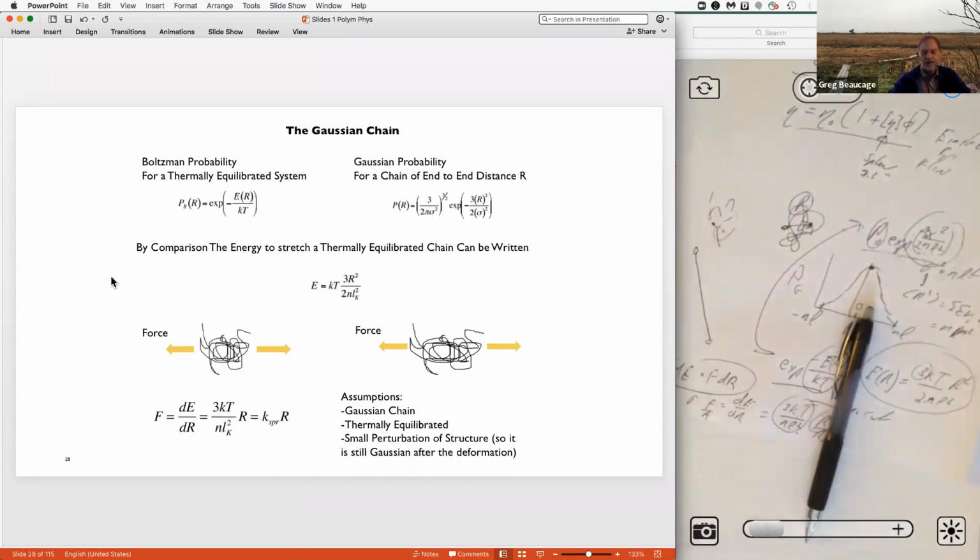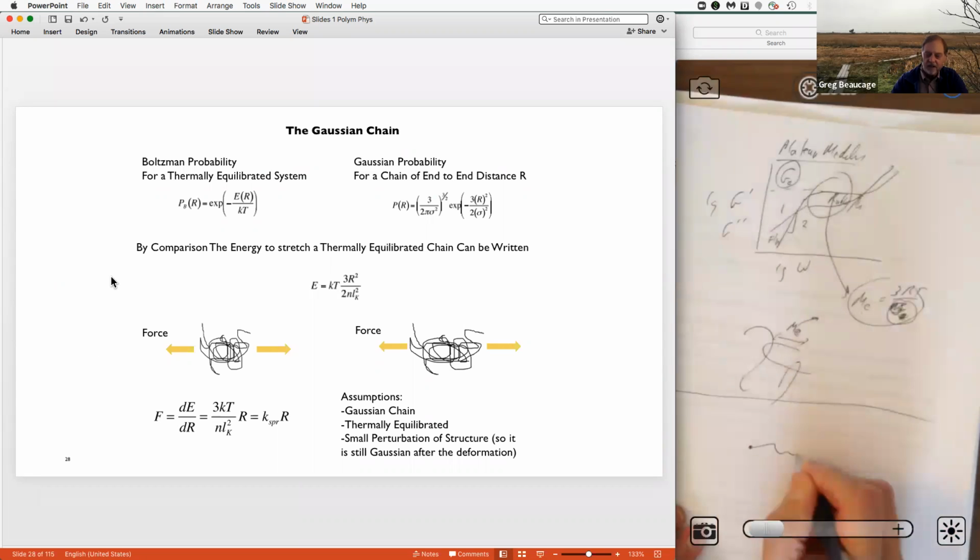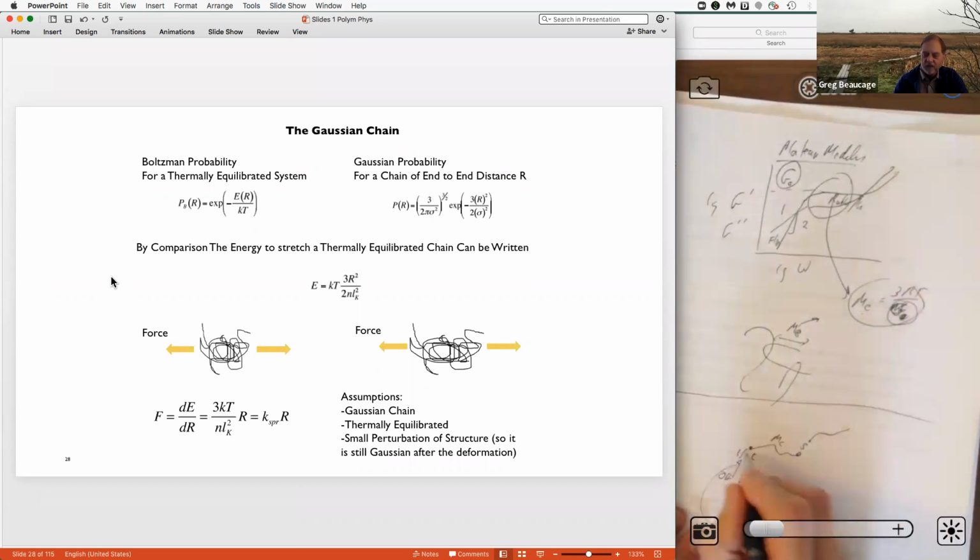So what it means is that you're going to make a rubber, and you're going to start with some chains that have functional groups on the end that can bond. Either you're going to put in sulfur so that they can link together, or you'll have some functional group like OH that can react, and two of these can get together and make water, so they can react to make a Si-O-Si bond in polydimethylsiloxane. Right, so you have some reactive end groups, or you just put in sulfur and link up the chains. Right, in the end, you're going to have some MC, molecular weight between cross links.